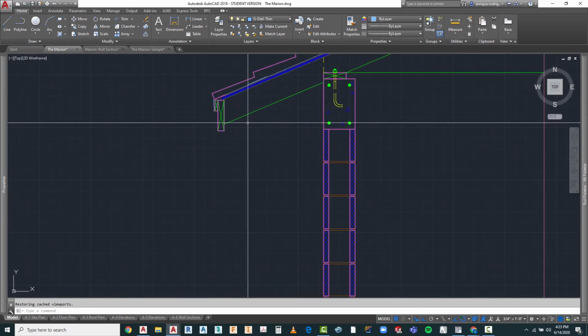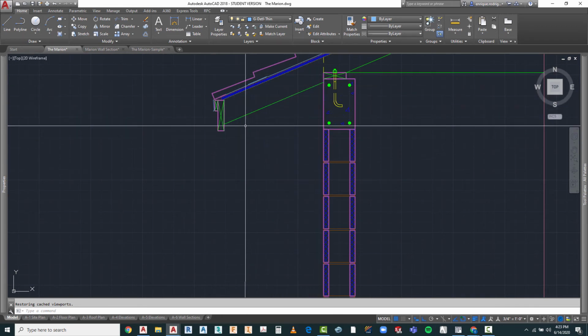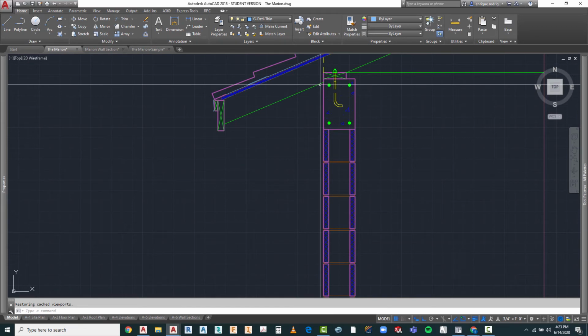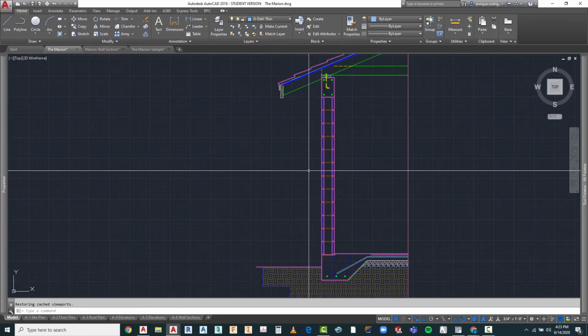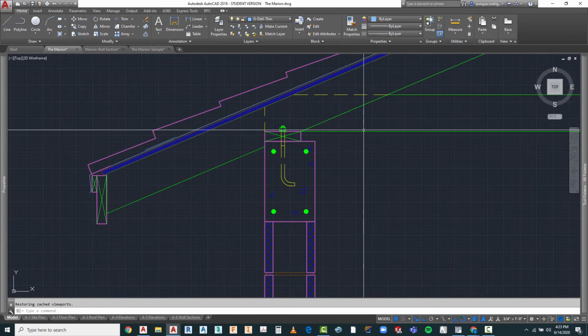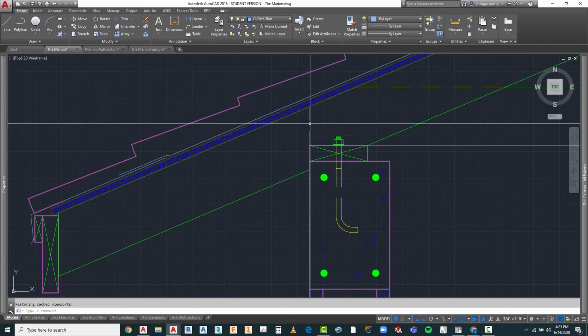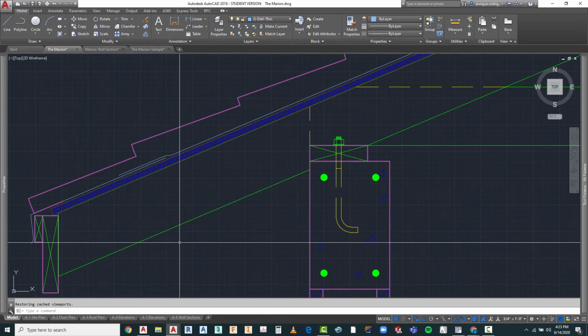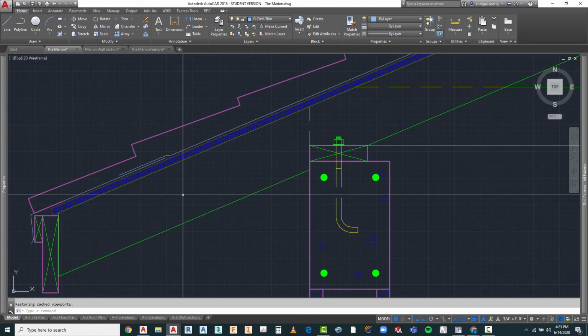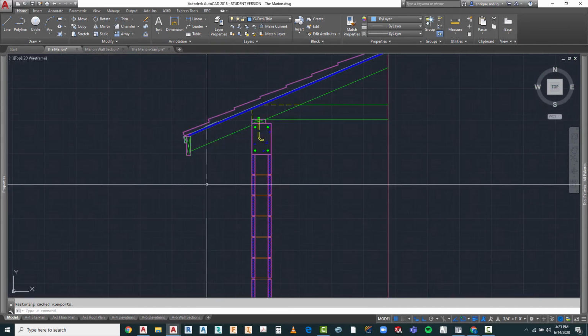So now what we're going to do is put our stucco finish. We have a stucco soffit along the bottom. We also have stucco along the outside. We're going to add our insulation here. We're also going to add what we call a baffle in here, which will allow for circulation to go through, since we have a vent at the bottom of the rafters on our soffit.